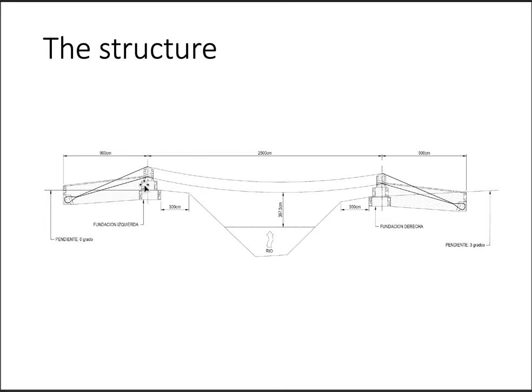Some of the things that we can modify here, we can add additional tiers here. So we have only one tier here. We could actually add 2 more tiers for a total of 3 tiers in order to achieve more vertical distance here. So let's say maybe the high water level was higher up. It was up here. And in order to get our freeboard, we need to raise up the tiers. So this is typically the only modification we really make, and that adjusts the size of your abutments.